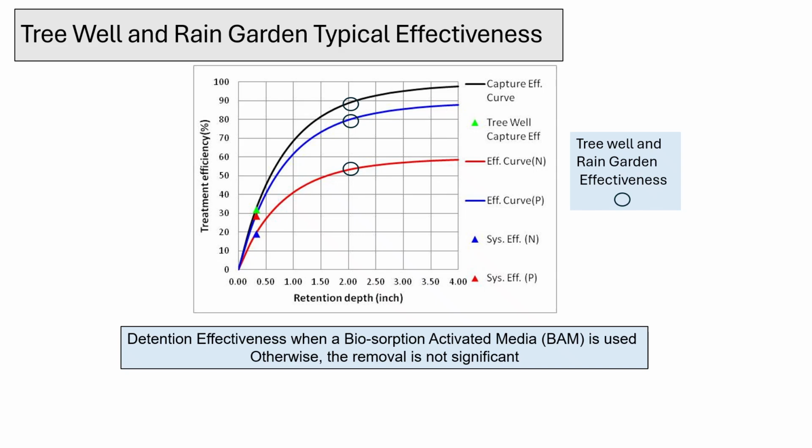Despite the relatively small footprint, the treatment effectiveness demonstrated impressive results, over 50% for total nitrogen and 80% for total phosphorus. This level of performance successfully met the surface discharge redevelopment performance standard of 45/80ths for this particular catchment.